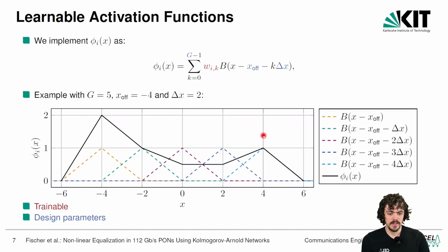Furthermore, the final function is a piecewise affine function, meaning that we have the advantage of only needing one multiplication for every evaluation of the function. However, this comes with a trade-off because we need to first perform a lookup step to decide in which interval of the piecewise function we are, and second, we need more memory to store the corresponding affine function values.